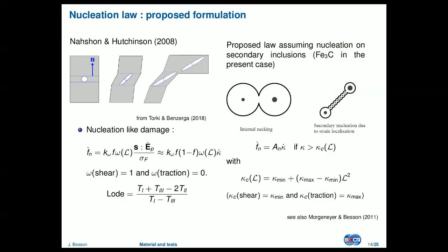So it's basically the problem of nucleation of damage at relatively low triaxiality, for load parameter values of about 0. There's this approach by Nahshon and Hutchinson, which is linking voids: the voids rotate, they elongate, and ultimately they touch each other and that forms a crack. The problem is that the length scale is the same as the length scale for the large voids, and we see small voids. So we just used a specific nucleation law.